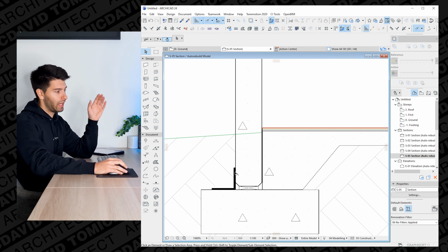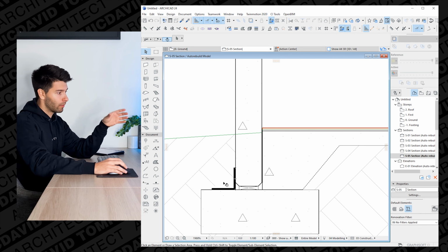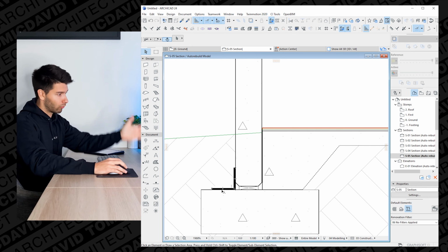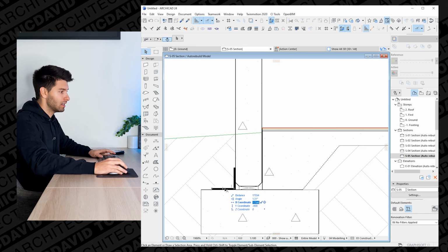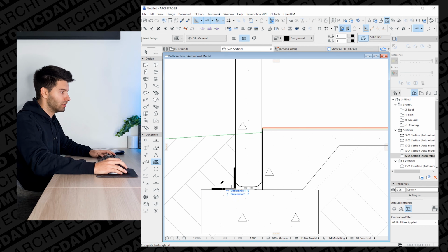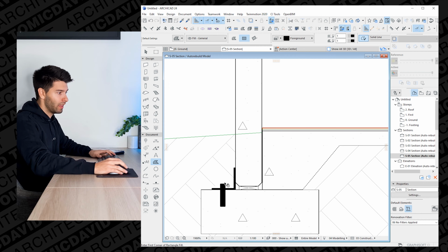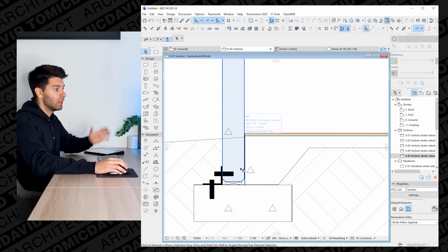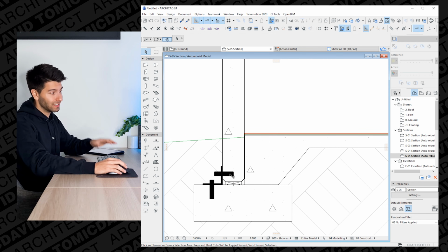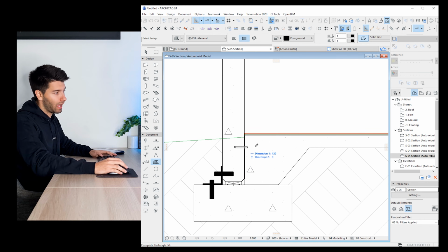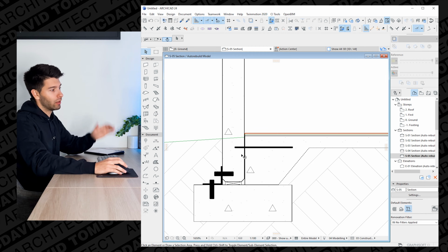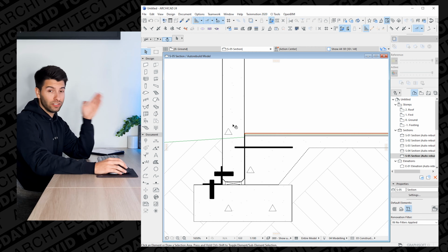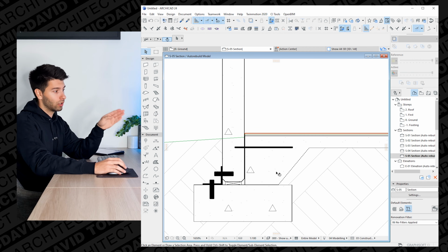So first of all, you would have that steel cleat along the bottom. The steel cleat would have a bolt running right through the bottom here. So for articulation purposes only, there would be a bolt right there. The second bolt connecting directly into this panel wall. That would be done on site once it's lifted, whilst you would also have a metal rod coming through the concrete tilt up panel and into the concrete slab.